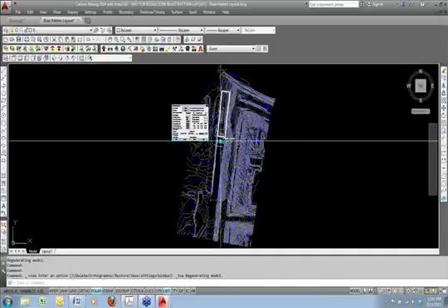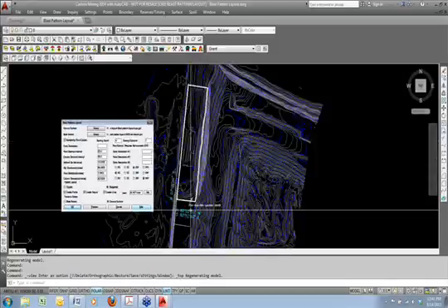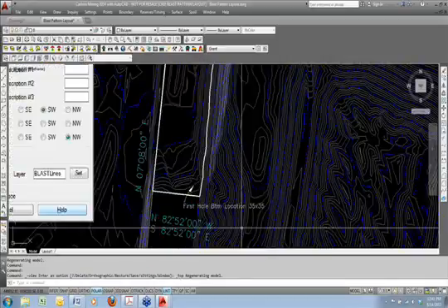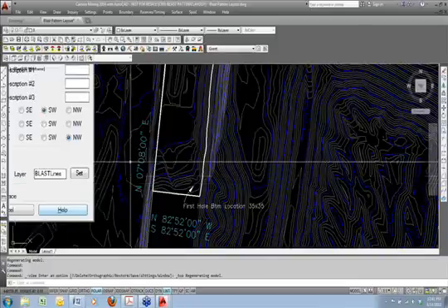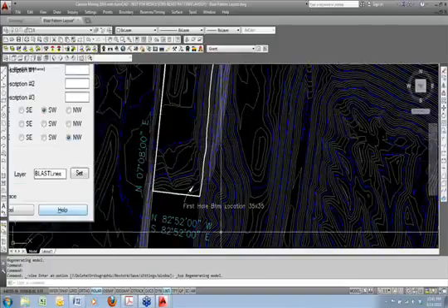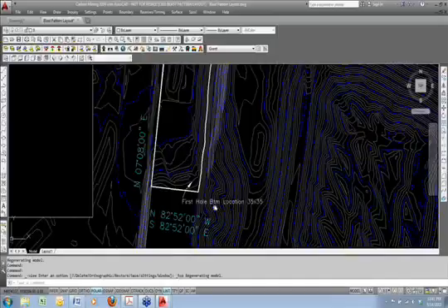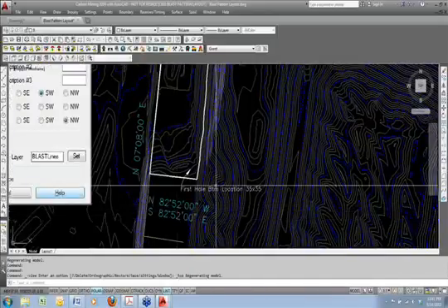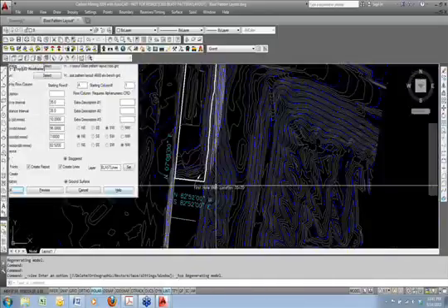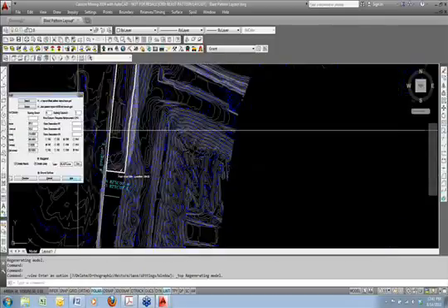All right, so I've got a perimeter. You first draw an outline, and then you also need to know the bearing. So my rows are going to go north 7 degrees east. My columns are going to go north 82 degrees west. And the same for the dip: I want the dip of my holes to go at that, we'll go with 10-degree holes.